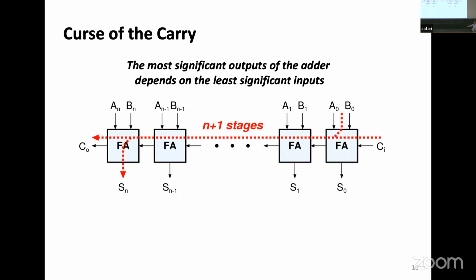So the first full adder takes A0, B0, and once all these circuits get their inputs, they get them at the same time. There are 12 full adders, first, second, third, fourth, and everyone gets all the inputs at the same time. Let's just take this guy. What will he calculate? There is no carry in coming, and he says 1, 0, so the sum will be 1, the carry out will be 0. The carry out is going this way.